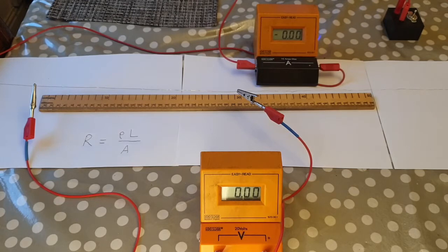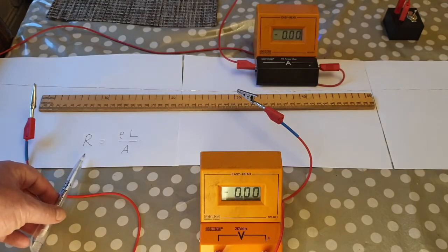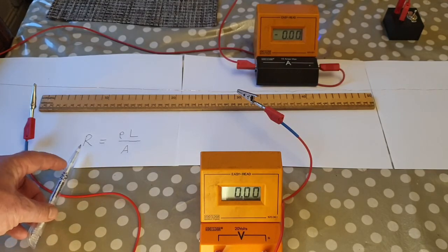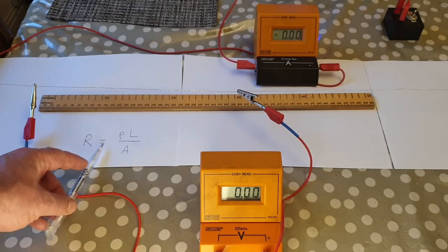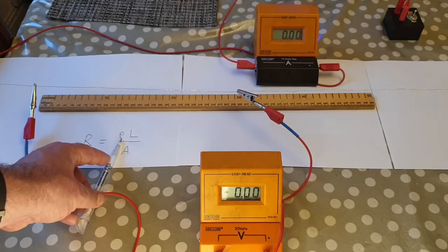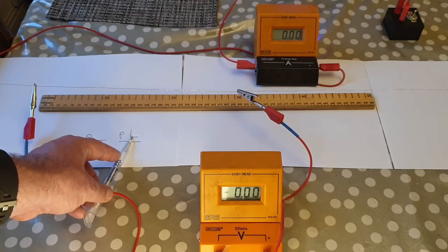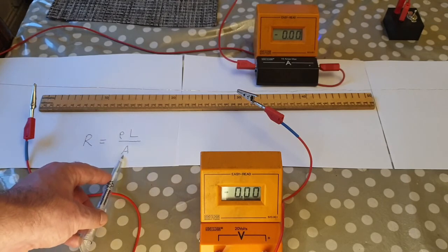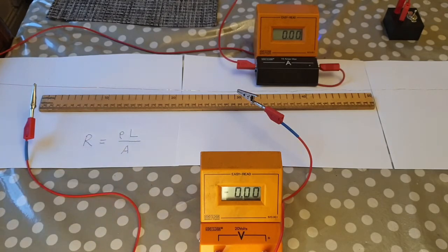You can go to a reference book, or you can go to Wikipedia if you like, as long as you cite the references in Wikipedia, and you can find out what the resistivity is of copper. Okay, it's a constant for a given material. So basically, this formula here, which you'll have to use, it's on the formula sheet, but you'll have to use it and learn what it means. The resistance of a wire equals this constant that depends on the material, called the resistivity, times the length in meters, divided by the area in meters squared.